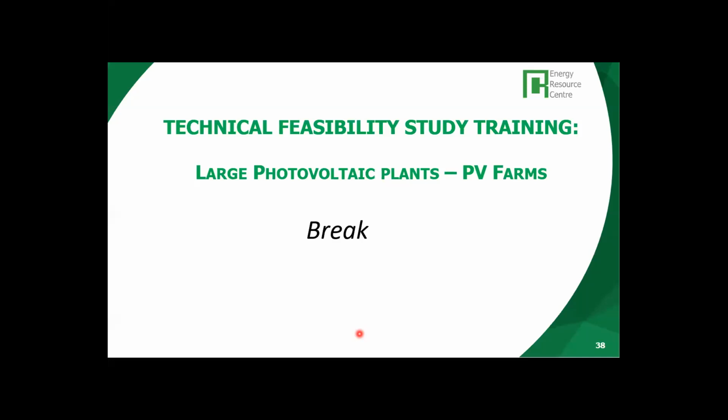You can use this reference: the solar panels are the elements that will require most of the land, so 1 hectare per megawatt is a good reference. Then you can easily integrate the inverters' space requirement as part of this same land reference, because the PV panels will require most of the land, whether they come with trackers or not.